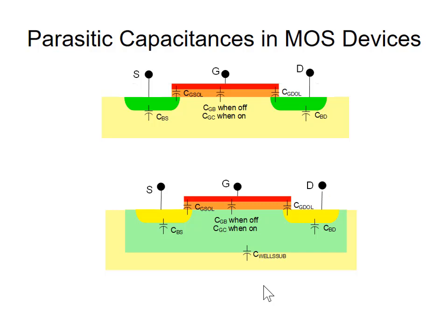Every capacitor in a circuit adds one pole. So if you have one transistor in a circuit, you've got 1, 2, 3, 4, 5 or 6 capacitors. And fortunately there might be a couple of loops in there. So you put one transistor in a circuit and you're already up to, if you consider all of them, third or fourth order.